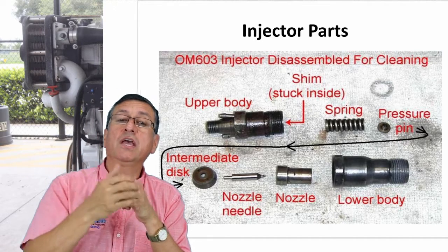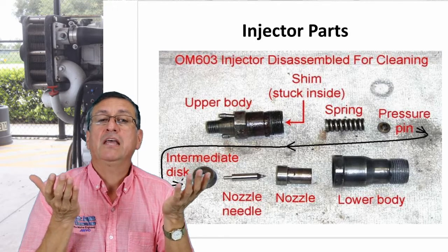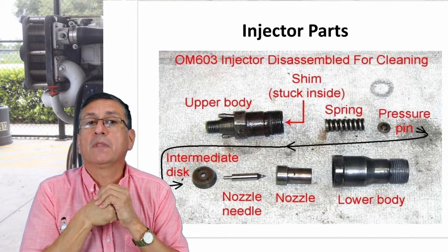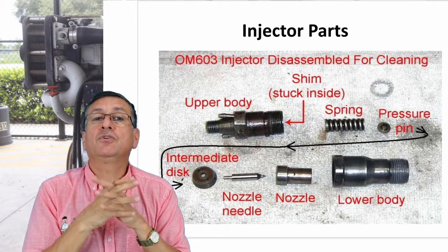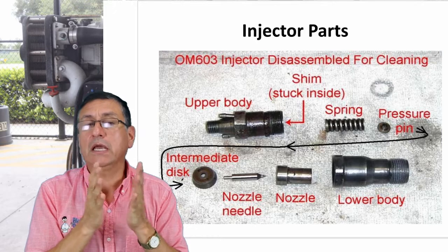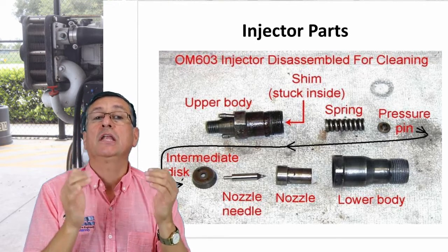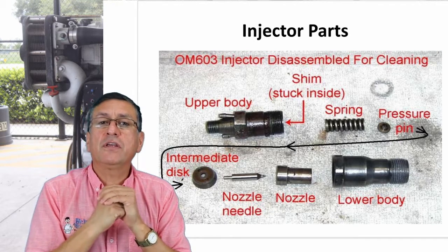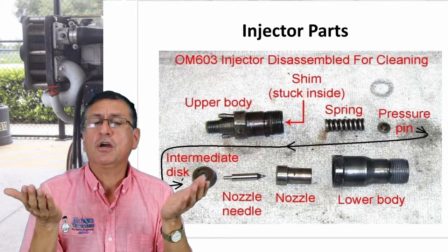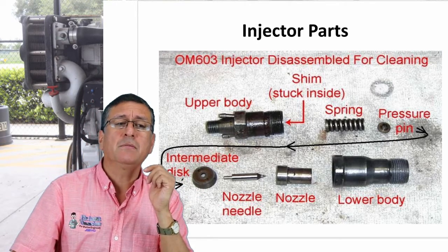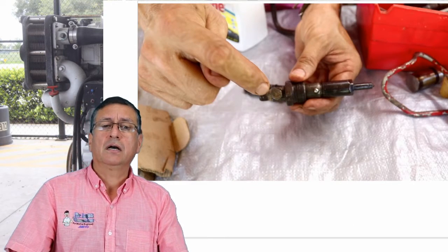One possibility is the injector. The injector opens partially, less fuel enters the combustion chamber, more air, less fuel, and the temperature increases because the mixture is lean. Yes, that's the consequence. Okay, in those cases, if you have a couple of cylinders running lean, probably you need service on the injectors. Okay, then the procedure is to send them to the machine shop, or you can replace them. Yes, you can replace. Let me show you the procedure to do that service.